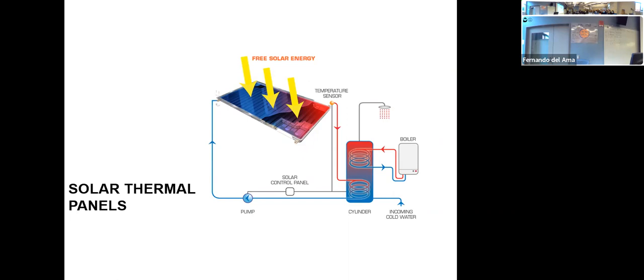And at the end, the water in the shower, we have something at 140 with cold water. No, X, but let's say 100 Fahrenheit. Something reasonable. But we need 140 to kill Legionella, a bacteria named after Roman legions, because when they went to conquer the rest of the world, they died because they drank water that was warm.